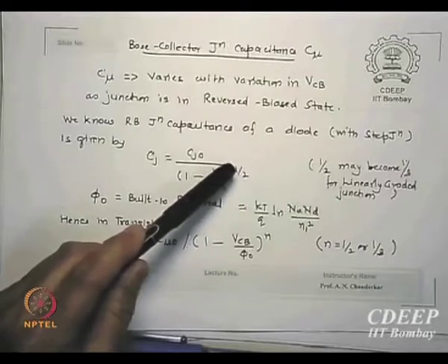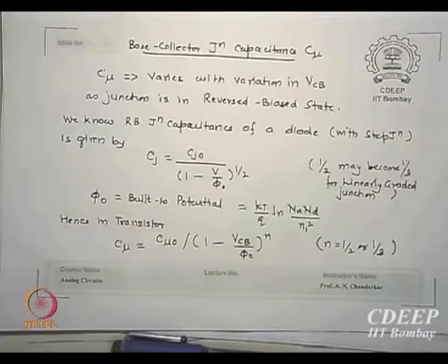This half is not very correct. Why is it not correct every time? Device theory says if it is a step junction, n is half; if it is linearly graded, it is 1/3 or 0.3 or something. Exponential will be further different in values, but assume for right now either of these. So I write n normally as linearly graded; for exponential, always assume linear.